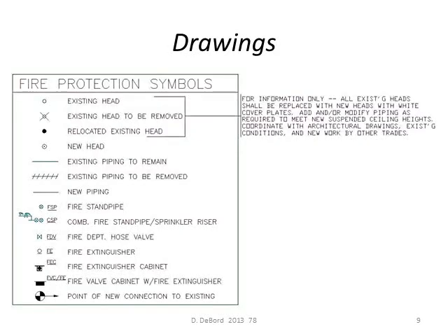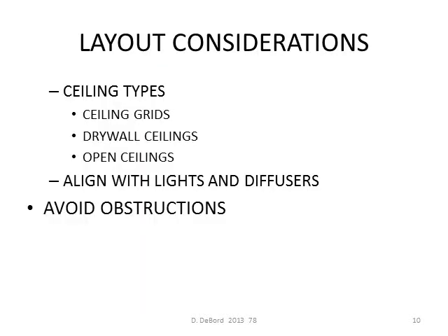Use some typical symbols. Normally, for fire protection and plumbing, we show the lines lighter if it's existing and heavier if it's new. Here with the existing piping and the new piping, it's not really showing a good contrast. There should be more contrast there. So you always have to make sure you look at the actual prints or deliverable, might be a PDF or DWF, and make sure that it's plotting the way it's supposed to so everything is clear.